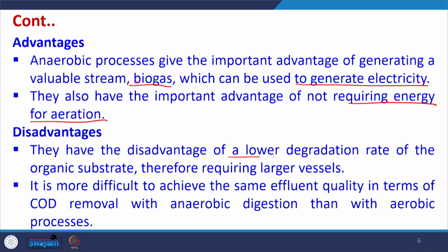The disadvantage is that they have a lower degradation rate of the organic substrate, and they therefore require very large vessels. So, the vessel dimensions may be bigger than in aerobic treatment processes. It is more difficult to achieve the same effluent quality in terms of COD removal with anaerobic digestion than with aerobic processes.